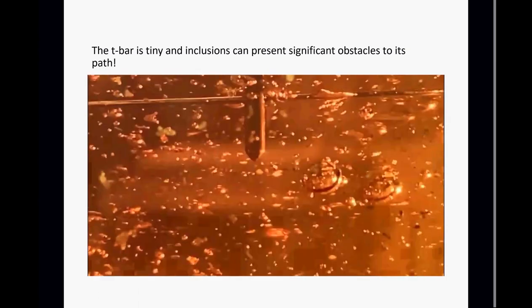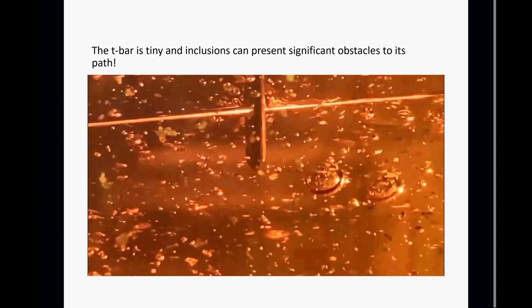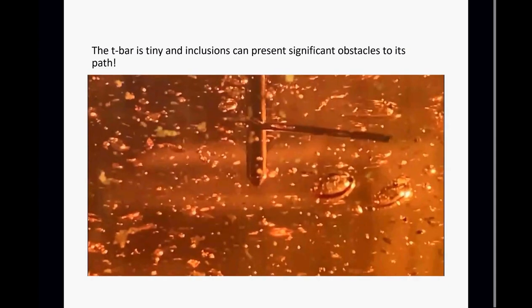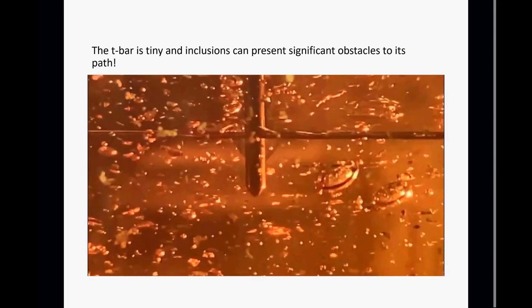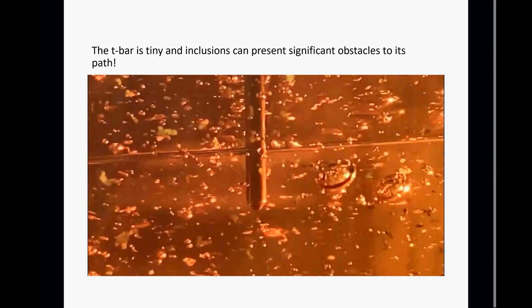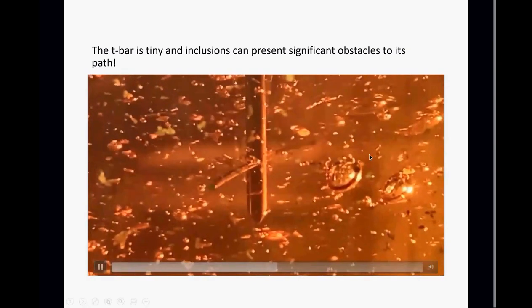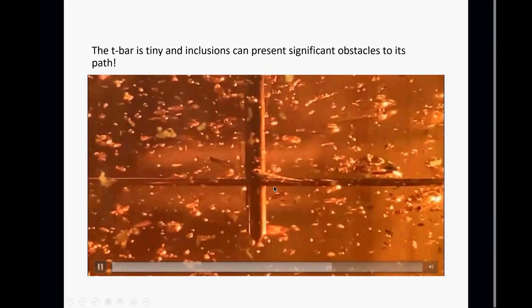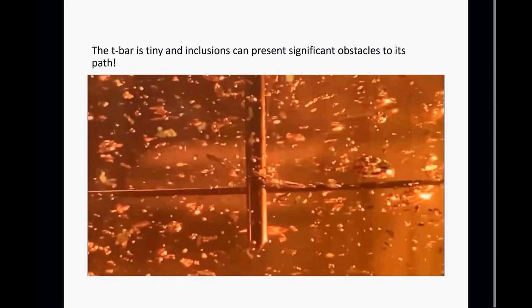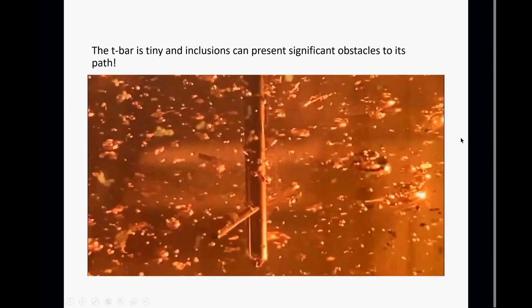So that's why it's always necessary to run this for around maybe a minute and take measurements maybe 10 seconds apart and then get a mean value of those measurements. The bigger the T-bar you can use, if you can use a T-bar A or B rather than the E or the F, then that's also going to give you a much more repeatable result on this. Okay then.